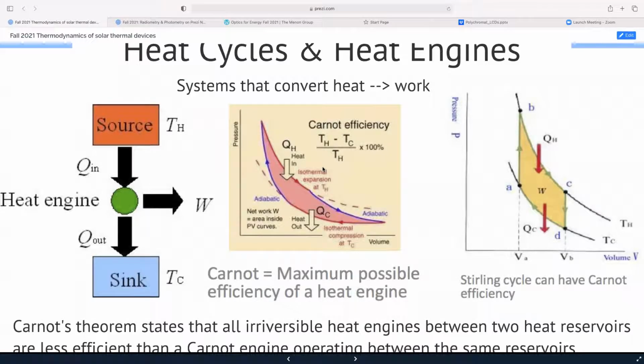It's not such beautiful curves as described here. So we'll start here. First of all, you have the isothermal compression, shown by this red curve. That means the temperature is fixed at TC, sorry, so that's the cold part. Then the gas is compressed. That is a situation when the heat is drawn out of the system.